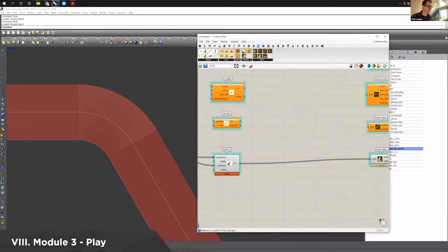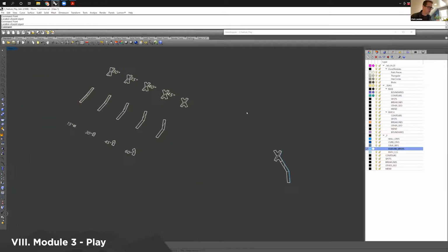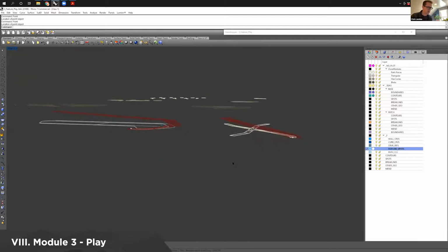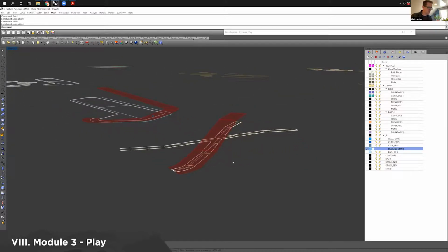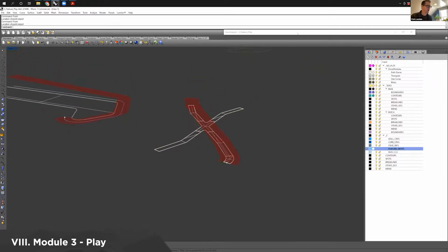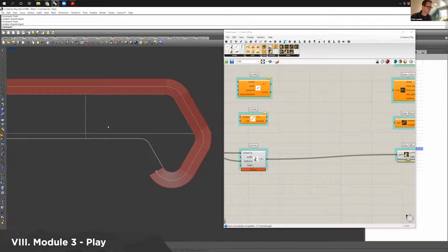And nice and smooth. Okay, so if I zoom in on this, I can see that my path starts at that bottom location and grades up. It grades at a slope of 5%.